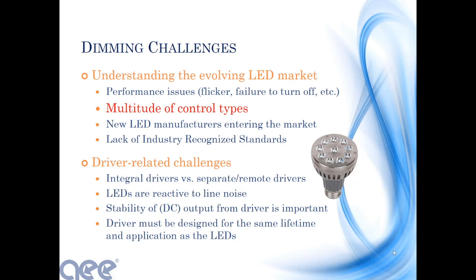So you would have an LED with 100,000 hours on the light engine, but the driver had a 40,000 hour life. And when was the last time anyone went up and changed the driver in an LED? They're not designed for that, number one. Number two, code didn't allow it. UL didn't allow it. It's only recently that there are temperature rated drivers similar to fluorescent ballasts, right?